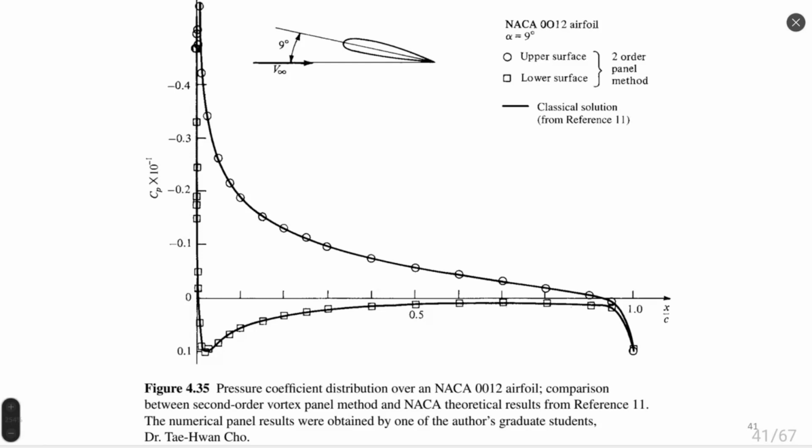But with all this effort, we can calculate viscous process, we can calculate boundary layer, we can calculate flow separation, and quite accurately. So there are advantages to CFD, and the main advantage of CFD is that you can use our fundamental equations directly to simulate flow. In the case of the potential equation and the result we obtained from the model we discussed today, we are not using this equation directly. It's an approximation.